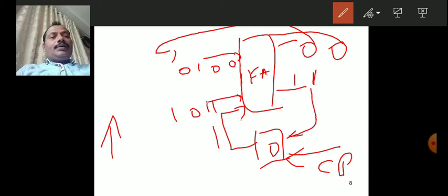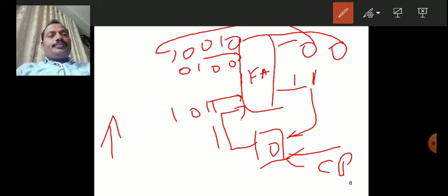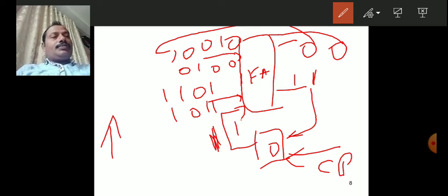Okay, let us write for the new case. Because the sum is 0, it goes to the MSB position, and each other bit is shifted: 0 0 1 0. And similarly here, the rotation of the Y number gives 1101, and the shifting of carry by the delay line is 1. Here we got 1. Okay, let us erase.